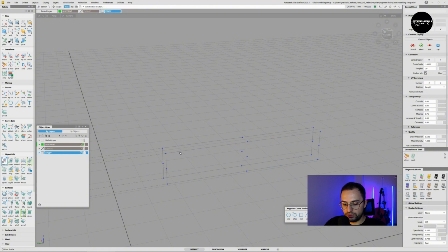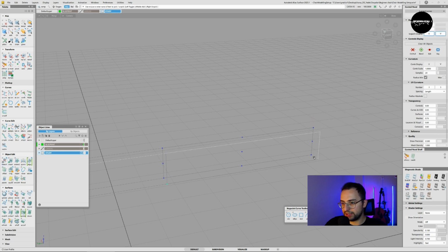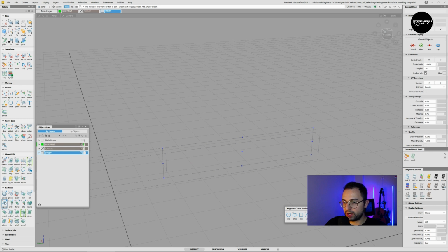If I hold Ctrl Alt and left click, it shows these pinky cross sections here, and hit space, once again hit space, and once again hit space. Now we have 4 different curves rather than a complete rectangle, because we needed that to use the square tool.